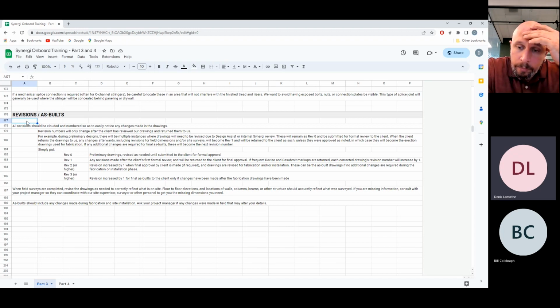It's very uncommon for us to ever have a drawing from the architect match the exact site conditions. There'll always be something that gets thrown off a little. Your floor to floor heights may be off. It could be as little as 1/8 of an inch, and you'd be very fortunate if that's the case. And sometimes we're off by inches. It could be an inch, it could be more. Maybe the initial survey that the architect did themselves when they did their drawings might have been off and threw everything design-wise out the window because the floor to floor is bigger than what they expected.